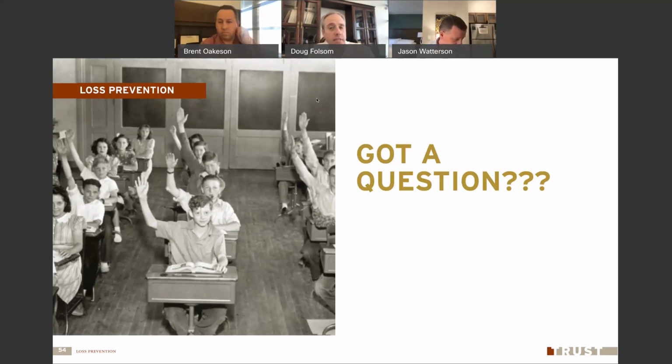Well, I've used these in my past lives. Working in warehouses, we'd use scissor lifts quite a bit. And I understand the temptation to reach out, to climb up the rail a little bit. I kind of liken it to our ladder safety training, where you've got that rule: keep your belt buckle inside the rail. I think that applies to these man baskets, to boom lifts as well as scissor lifts. Brent said, keep your feet on the floor. Don't get your belt buckle up over the top of the rail or outside of the rail. I think that's another good way to think about that, to make sure you don't have that accidental fall.